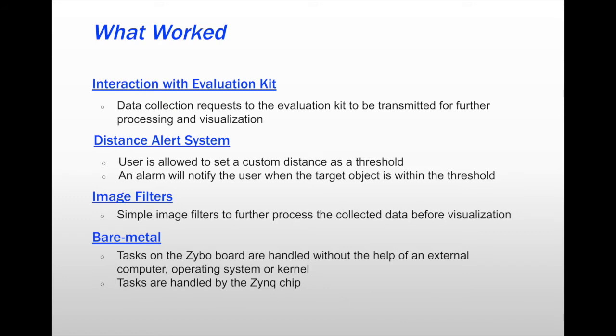Finally, we were able to successfully implement the majority of the system as a bare metal application, which means that all of the aforementioned tasks on the Zybo board are handled without the help or overhead of an external computer, operating system, or kernel, and is instead carried out by a minimum amount of resources made up by the programmable logic and processing system partitions of the Zynq chip.